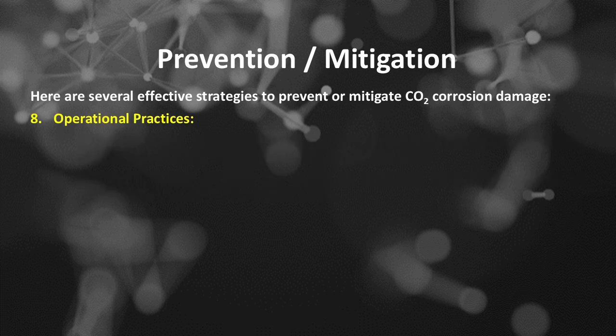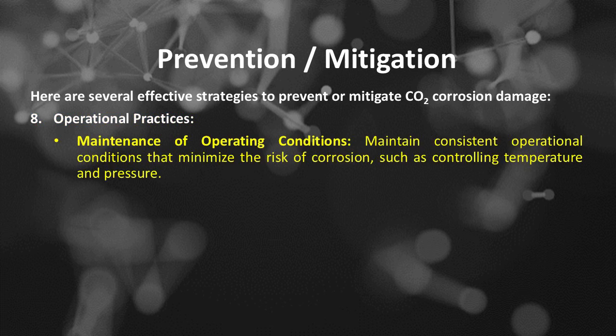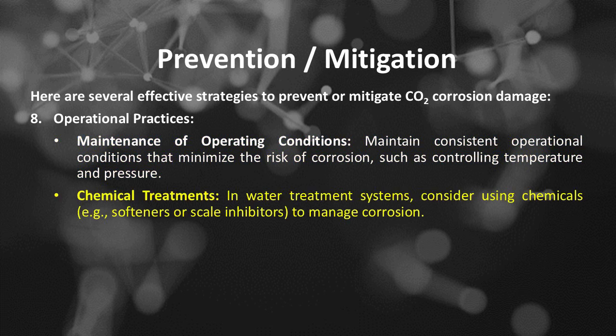Number 8 is operational practices. Maintenance of operating conditions. Maintain consistent operational conditions that minimize the risk of corrosion, such as controlling temperature and pressure. Chemical treatments. In water treatment systems, consider using chemicals, such as softeners or scale inhibitors, to manage corrosion.